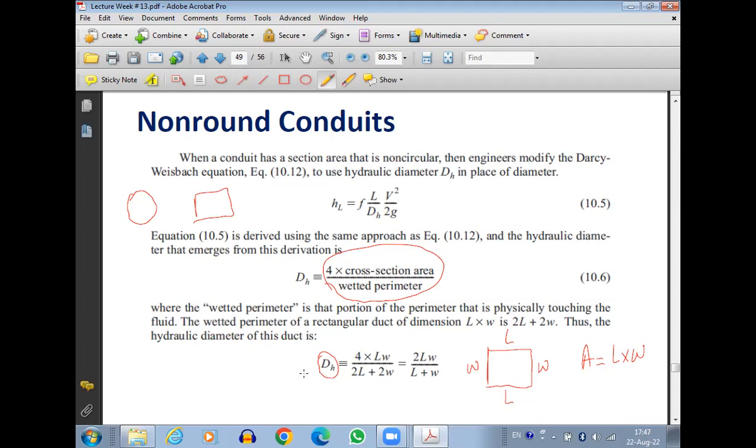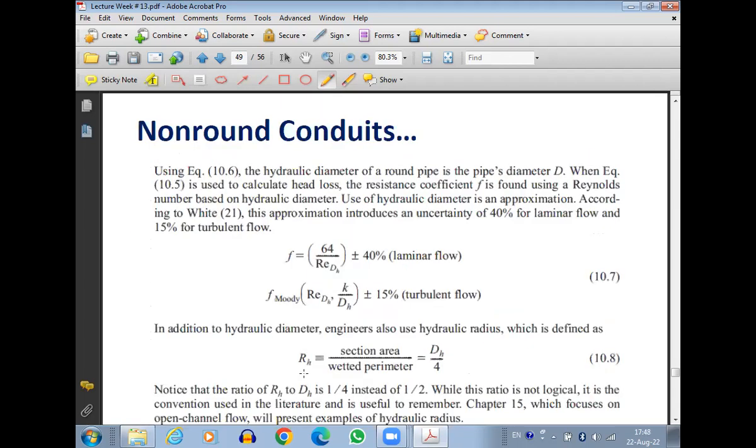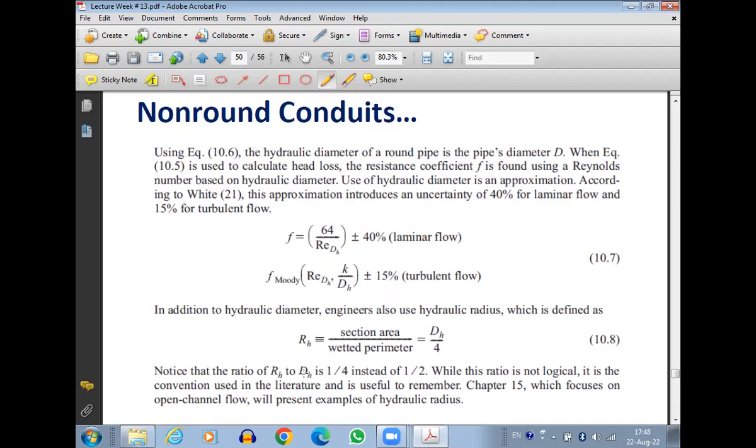Okay, because these ducts are not carrying water. Normally, these ducts are carrying air. So we need to have a large size of the ducts. So large size circular ducts will be difficult to handle compared to the rectangular ones. They fit into the space much more compactly. Aesthetic requirement is very important there. Especially in the construction industry, aesthetic requirement, how it looks, is very important. Secondly, it saves area. You can have two rectangular ducts close to each other without wastage of area. If you have two circular ducts, there is a lot of wastage in area.